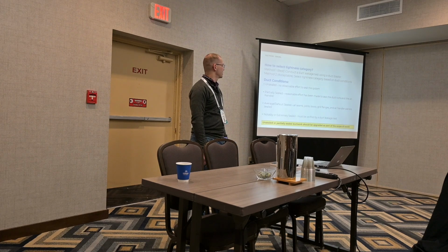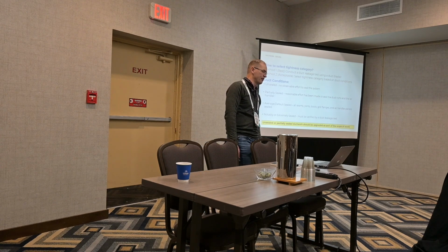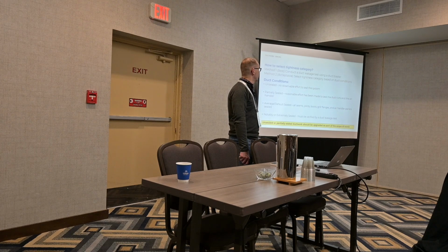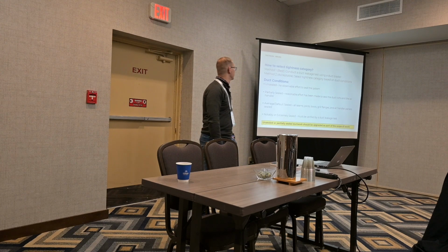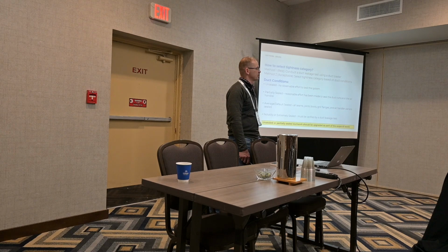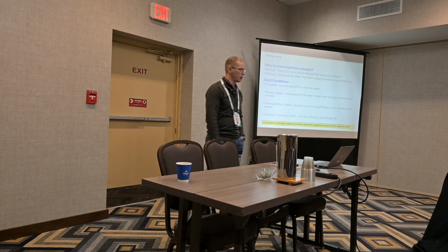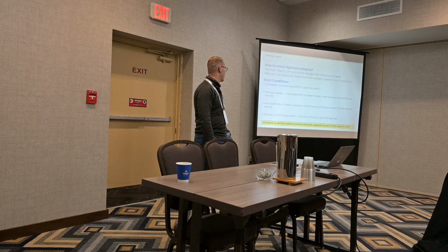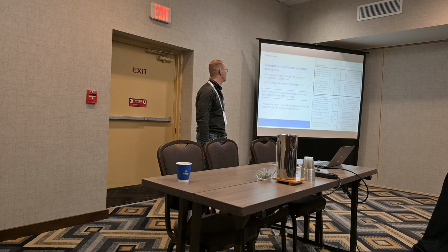Okay, how to select the tightness category. When a building is looked at for whether it is average, loose, or tight, and there are in-between phases on that, first conduct the duct leakage test using a duct blaster, and the second step is to select the tightness category within the Manual J. Those range between unsealed, partially sealed, average, and notably or extremely sealed, and there are a lot of values associated with that.